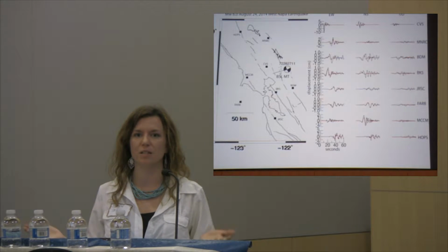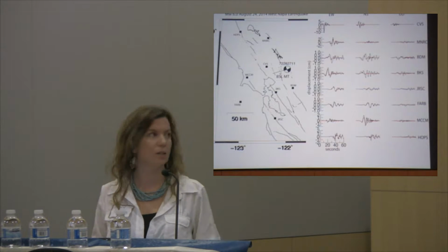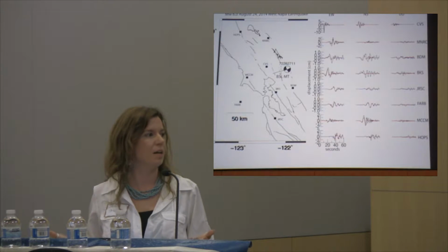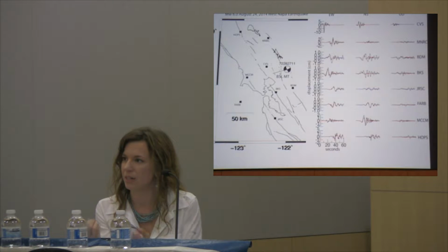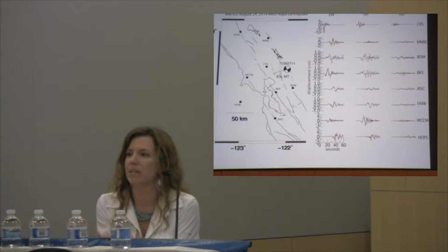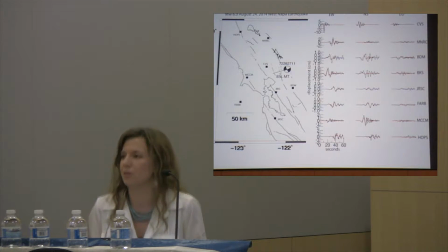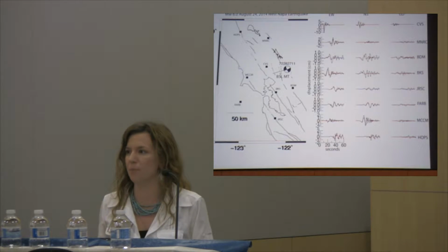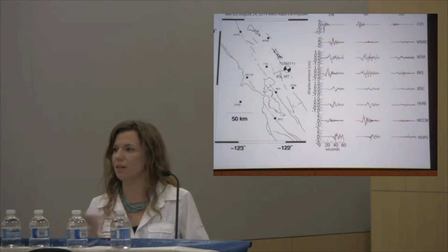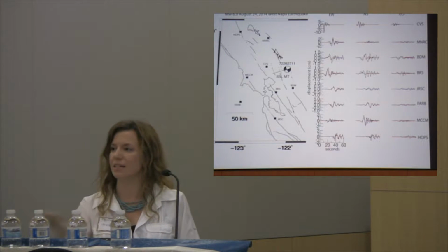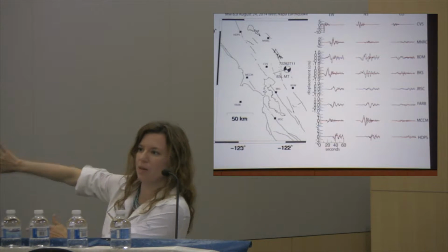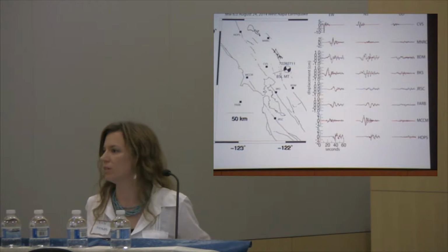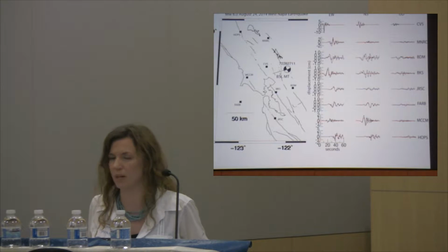The first wave front is a P wave, it's a compressional wave, and I almost put this figure in. The earthquake starts underground, and so the biggest P wave is the one that's coming under you, vertically, so you get a compression wave up like that. The second wave front is the S wave, and these are the transverse waves. These are the ones that start going side to side, and that is the wave front that begins the damaging shaking. The P wave, for all intents and purposes, is not going to do much.